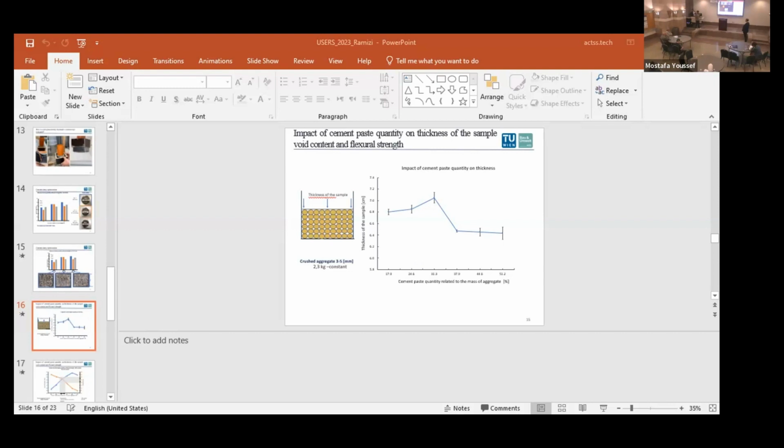To be honest, my first goal was, because when I got the topic, the question I asked myself was how it is possible to have so much void content. My first goal was to achieve the mechanical properties and the water permeability, and I'm quite optimistic that it can even be produced in a factory. Regarding frost and thaw, clogging, abrasion and the heat island effect, as I said before, this whole mix design should still be investigated and optimized.